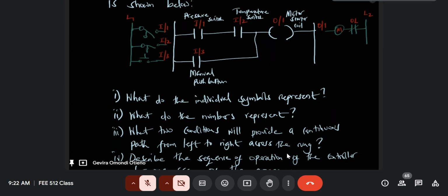And that's why our scan cycle is, you read, what are you reading? You're reading instructions. You execute, what are you executing? You're executing the expression from the instruction. And then what do you do at the output? You update what the state of the output is. Okay, so you read instructions, you execute that expression, and then you update the output.